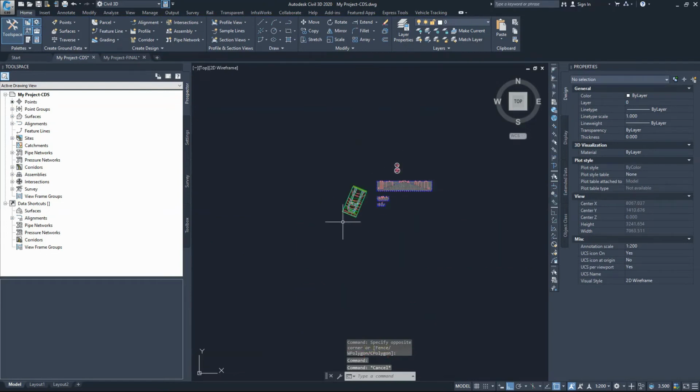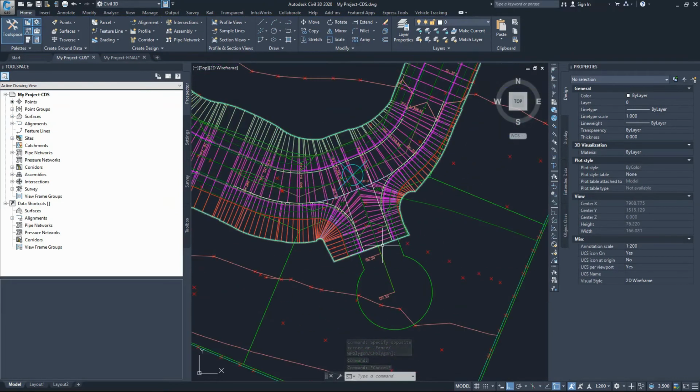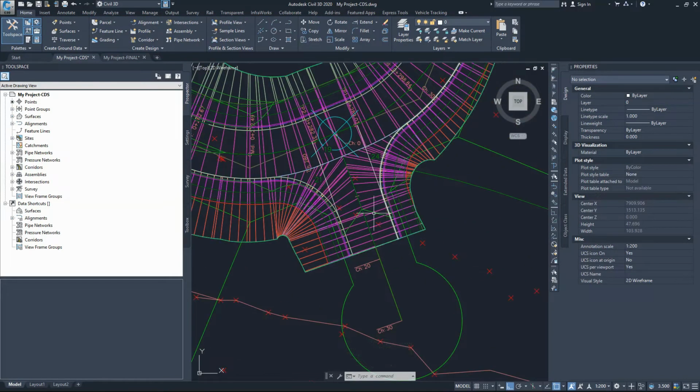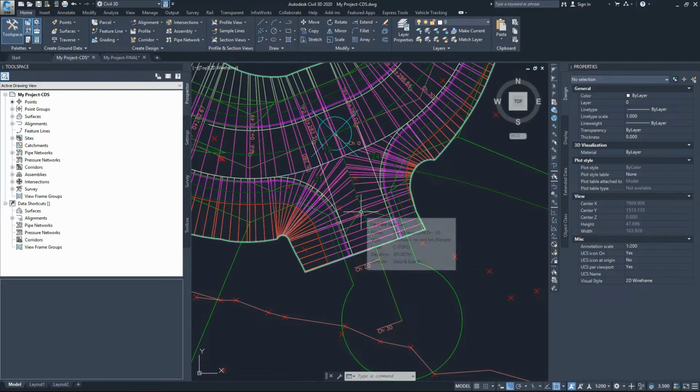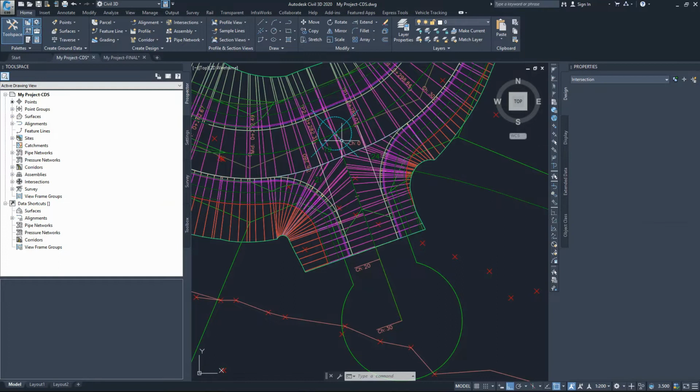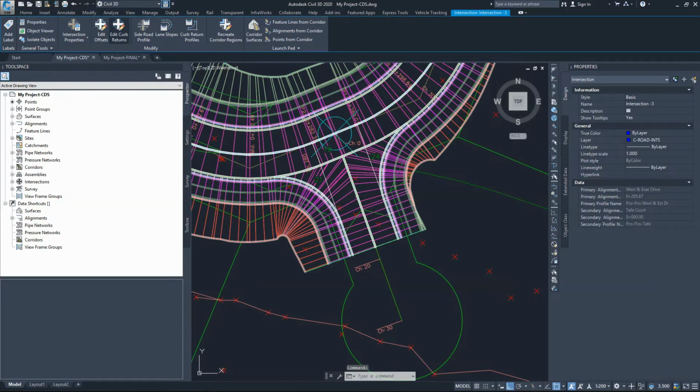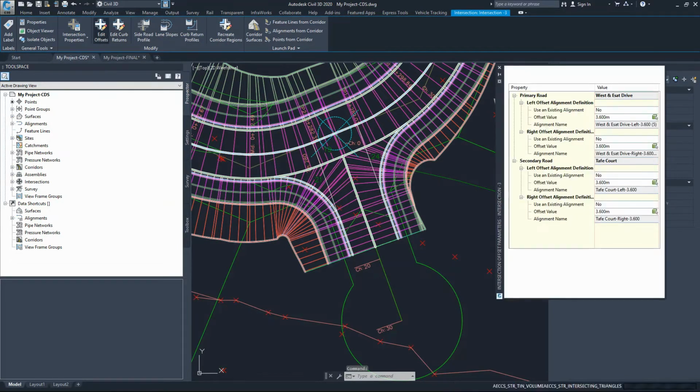Okay, now let's go back here. First of all, we need to, as we agreed, narrow this area here by 5 meters, 2.5 each side. So I start with, I need to go to the intersection that we designed and change the offsets on the side road only.